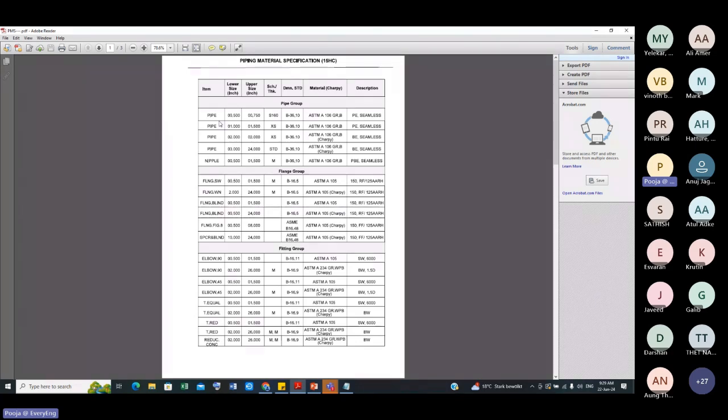If I want to buy a pipe, what are the things which I should tell the vendor? I want this much size pipe, 1-inch size pipe. I want 10 millimeter thickness. I want the pipe as per this standard. What should be the end connection of a pipe? It should be the plain end or the butt welded end. And how the pipe should be manufactured, seamless or welded.